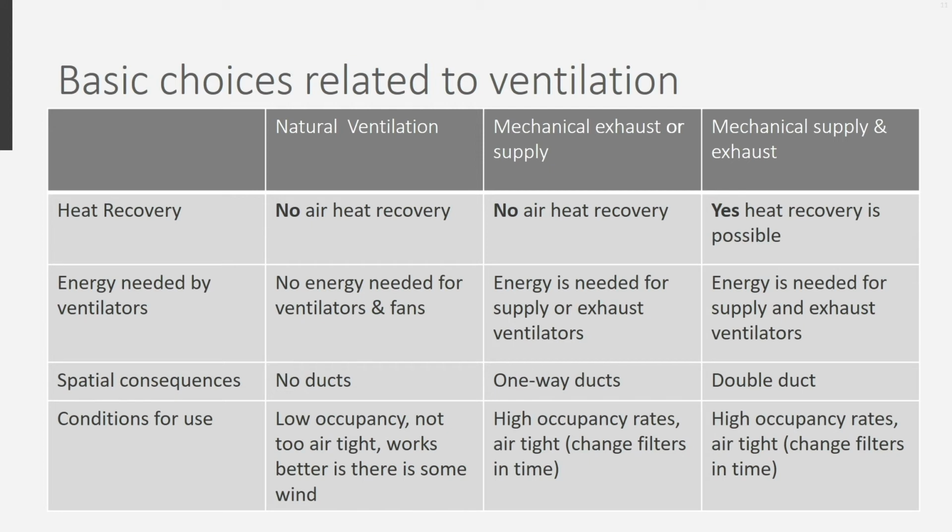Further, there are the ventilators. Those make noise, some more than others, and it's essential for the comfort of the occupant that the noise level is as low as possible. So the choice and location of these ventilators in the building is extremely important. Additionally, these systems are generally equipped with filters that must be changed or cleaned regularly. Otherwise, the indoor air quality could decrease drastically.